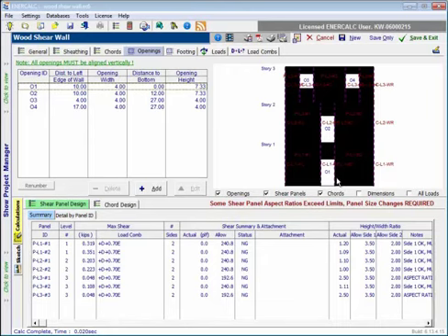And we go through the proper math to determine what the story shear is applied at the top of story 1, and then we attribute that shear to the however many panels are effective at resisting that shear in proportion to the length of each of those remaining effective shear panels. Notice also with the dotted lines that we define chords at these locations, because when we split the wall into effective panels, the individual full height shear panel method dictates that we have to have chords at both ends of all panels.